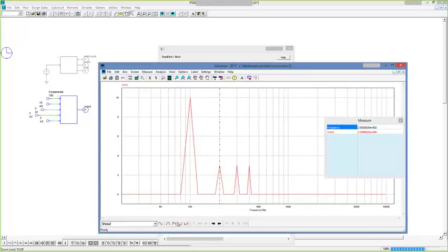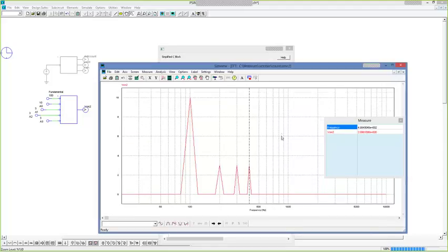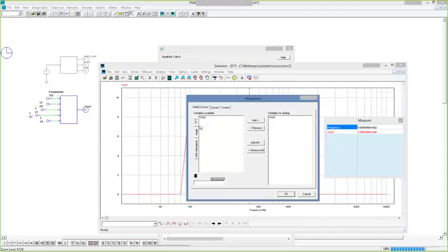So then we can quickly find the various other values here, and we can see the frequency response that we worked out. So we managed to find these 3 amplitudes at these 3 frequencies. We can also plot the angle if we wanted to, and we can also overlay EMI standards onto this plot if we wanted to look at what these things would be.